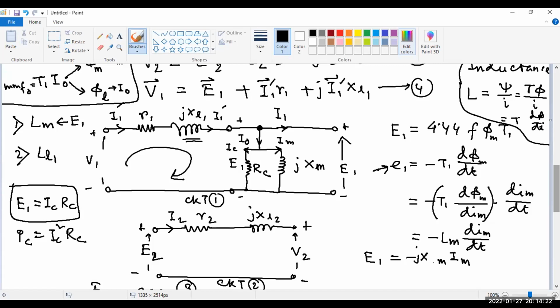Am I right? From the no load test, the ammeter reading directly represents the no load current. From the other two readings, the voltmeter and wattmeter readings, you can estimate the value of the no load power factor. Got my point?